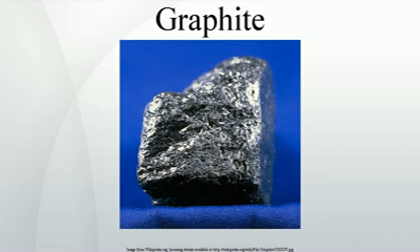Kish is a large volume near molten waste skimmed from the molten iron feed to a basic oxygen furnace, and consists of a mix of graphite, precipitated out of the supersaturated iron, lime-rich slag, and some iron. The iron is recycled on-site, leaving a mixture of graphite and slag. The best recovery process uses hydraulic classification, which utilizes a flow of water to separate minerals by specific gravity. Graphite is light and settles nearly last, to get a 70% graphite rough concentrate. Leaching this concentrate with hydrochloric acid gives a 95% graphite product with a flake size ranging from 10 mesh down.